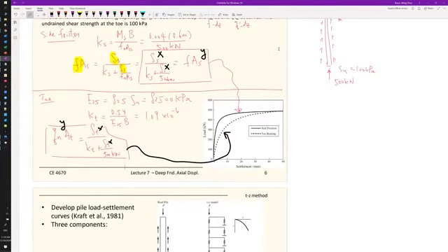So here I just want to break down how we approach the pile settlement issue. It's complicated because now it's the stress-strain relations of these piles, soil reactions, and interaction phenomena. So it's no longer one dimensional. Everything is two dimensional.